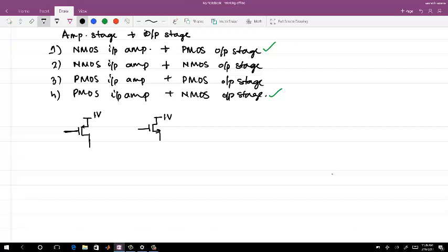So we are looking at this as V out. Assume that you have only the control voltages, which are limited by the supply voltage between 0 and 1. Let me not go beyond 0 and 1 volt. In which case you will have a V out which is higher. The only thing is you need to keep this current source in saturation. So in the case of PMOS, you can have a higher V out.